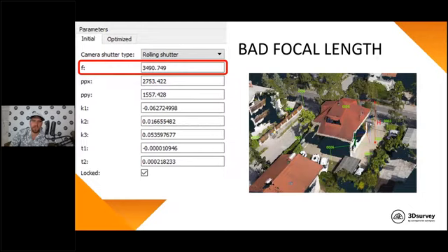Since the building is 10 meters high, that would mean we would only calculate it to be 9 meters high. So you can see that this one is the most important parameter to have. This is allowed because the other distortion parameters can distort the picture so that everything will still fit together. And because we don't have any ground control points up here, our model might look perfect, but it actually won't be.